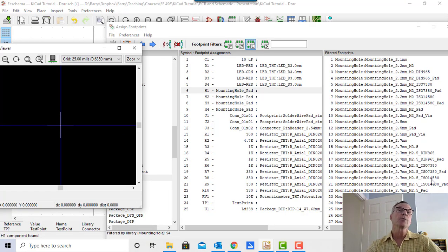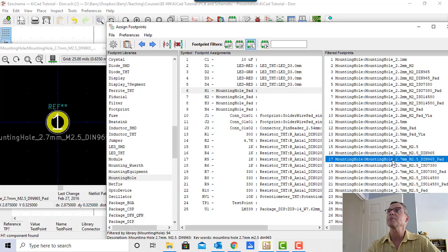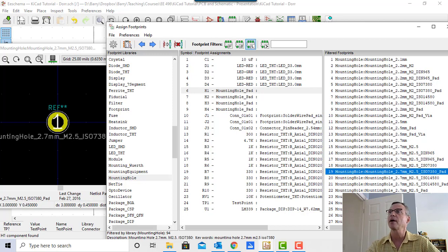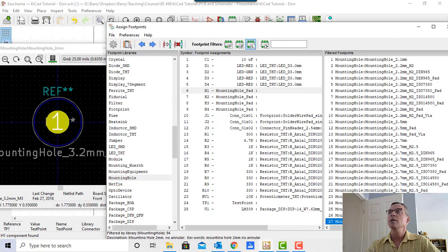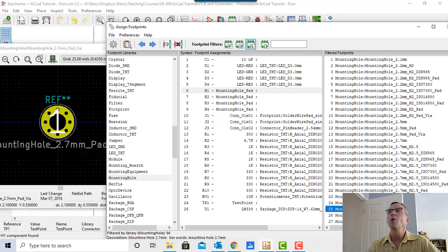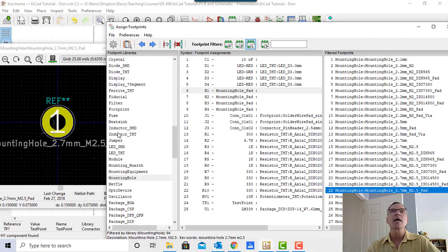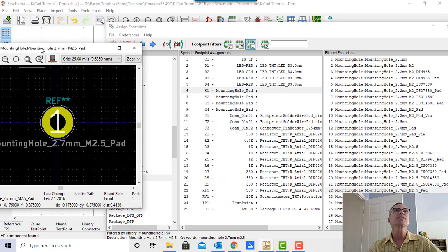And in your mini projects, you're going to have mounting holes with clearance for a number 6 screw. And I'm going to leave that up to you to cut through here and find that. And then in your demonstrations, we'll make sure that we can put a number 6 screw through there and it has a nice clearance. What we're going to do for now is we're just going to pick one. And we're going to pick this one right here. Looks about right. Let's actually see how big it is.